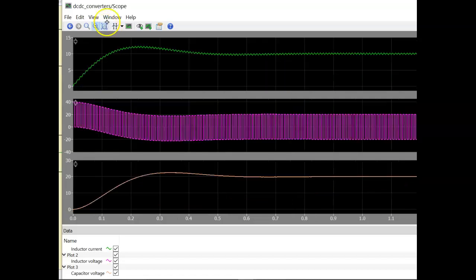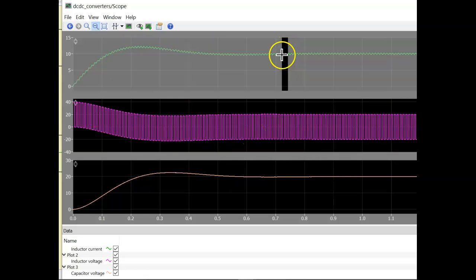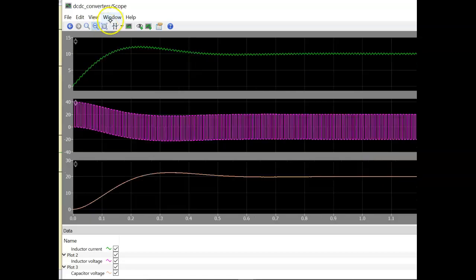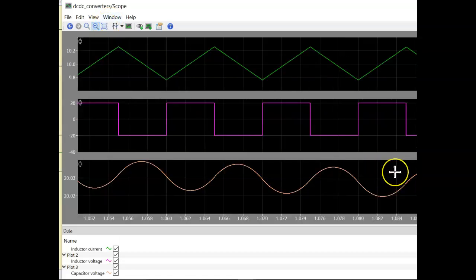but as a few cycles pass, the negative voltage that appears across the inductor in the 1 minus d Ts duration slowly increases like this, and finally it will reach a steady state value, and the inductor current in steady state looks like this. Still the capacitor voltage has not reached steady state. So if we go a little further, we will be able to see the steady state in the capacitor voltage also.